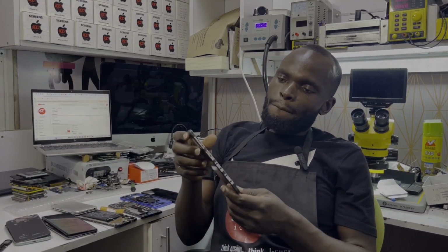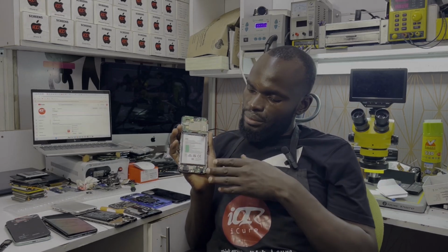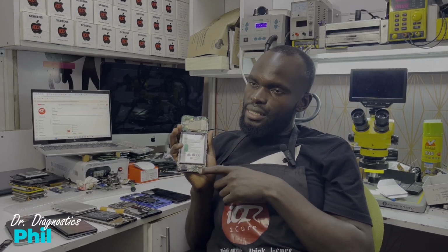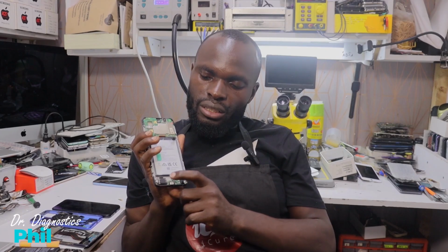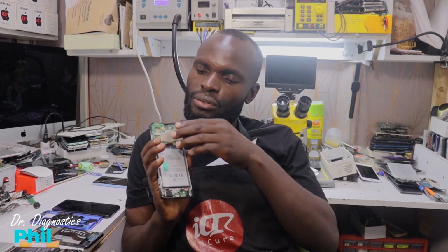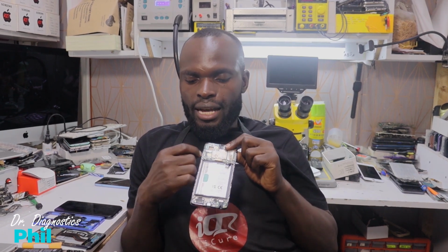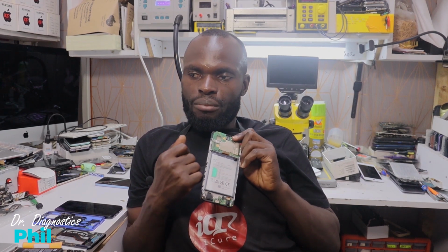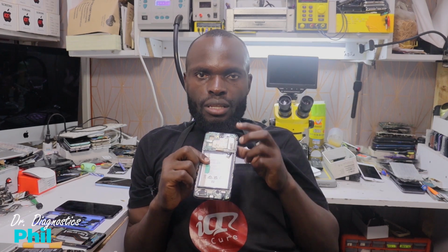I have said most phones, this is the structure. The mid section contains the battery. The lowest section contains the subboard. This is called the subboard or the charging plate or the daughter board. There is a ringer too here. Then we have the main board here, the motherboard, the earpiece, and the switch by the side. We have the inner switch and we have the outer switch that is located on the frame or on the housing of a mobile device. We also have the FPC that links up the subboard to the main board.